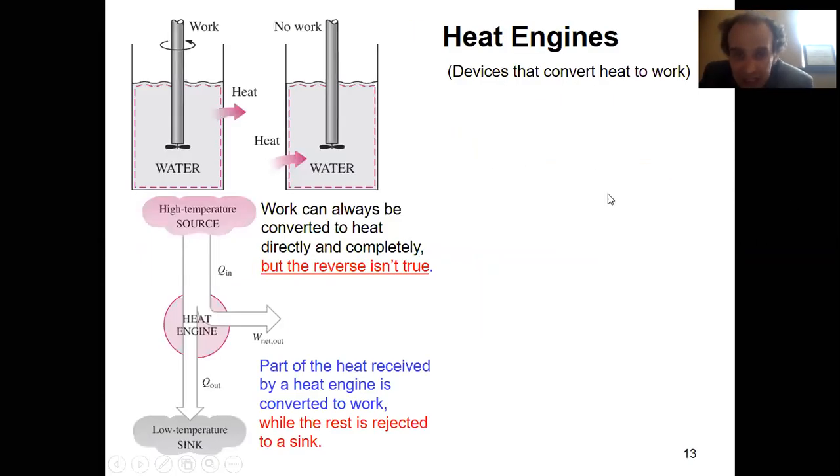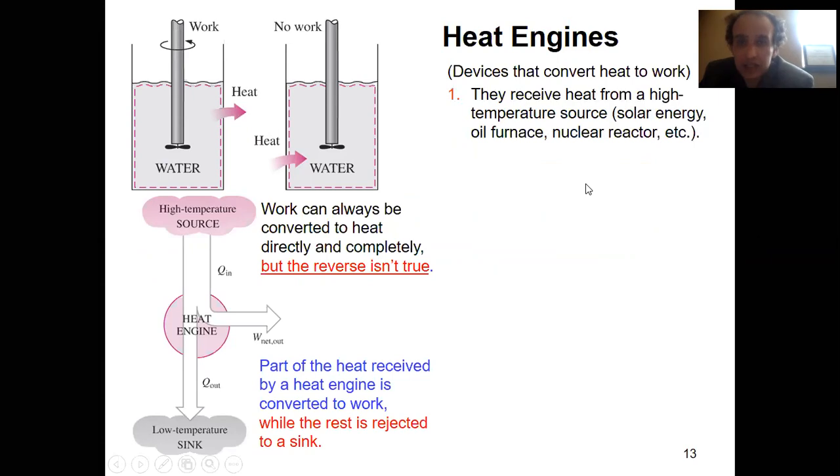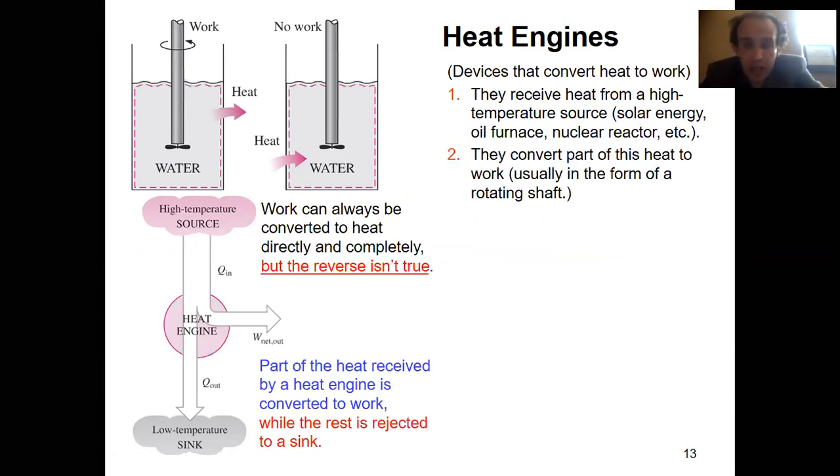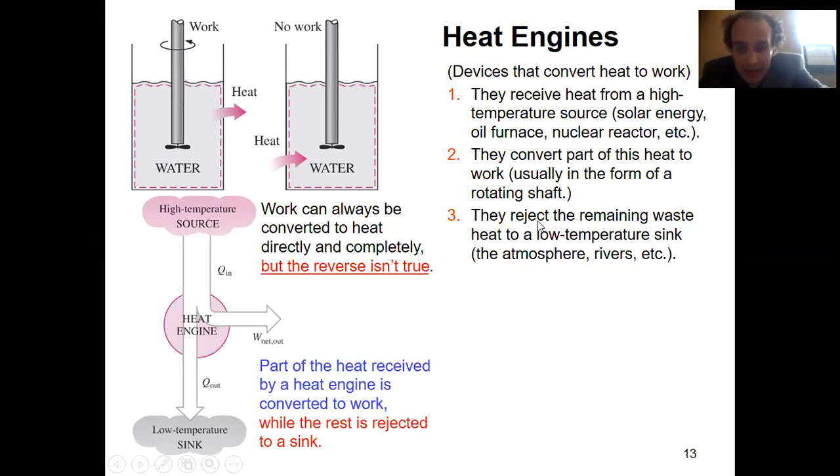I recall heat engines are not necessarily engines. So what is a heat engine? It's any device that receives heat from a high-temperature source, let it be the sun or a furnace or whatever. It converts part, not entirely, but part of this heat into work. That's what you want to get. But it rejects the remaining heat into a low-temperature sink, and this is unavoidable. It operates over a cycle like this. Do you see?